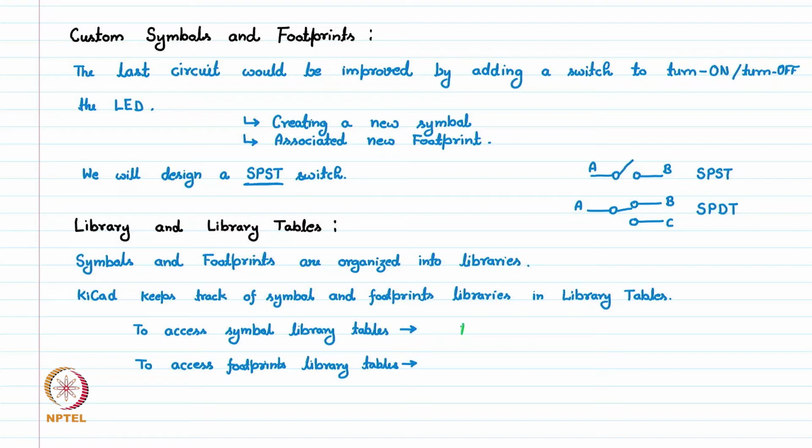You can go to Tools, Preferences, and then Manage Symbol Libraries.